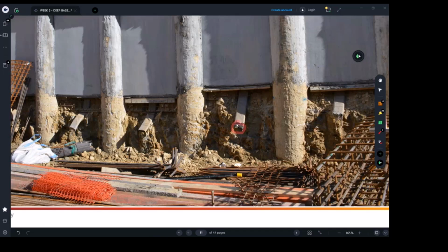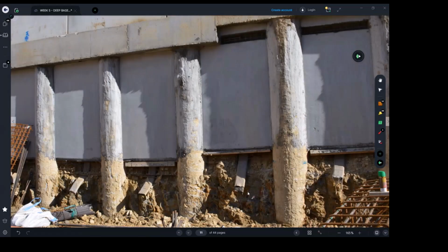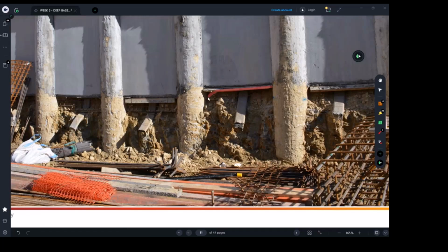There is a kind of splice connection. You're going to connect an extension to the strip drain and take it all the way down below the basement level to connect with the stormwater system. Right? So where we are at, yeah, that's it now.